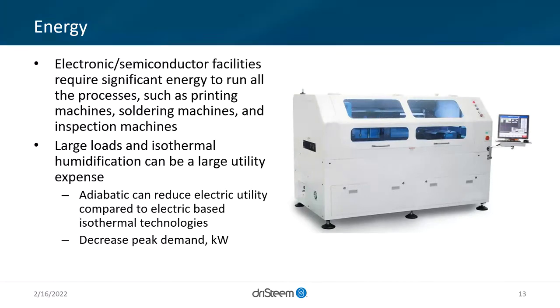And I want to do some trimming with an electric unit because the turn down is that much greater. So there are solutions like that to mix and match depending on the goal, where we get a bulk done with adiabatic because it's energy saving, and where we want that fine tuning at a very specific spot with, let's say, an RTS, resistive to steam unit.